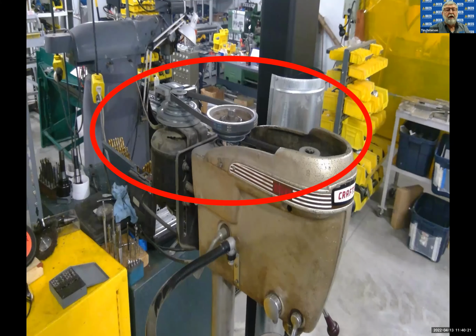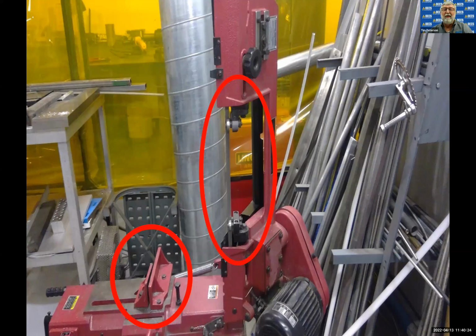The next machine guarding issue that Melissa's going to switch to is one, again, that a lot of people forget about. And this is on a bandsaw. The concern here is, if you look at the two circles, where that piece of metal is placed on the bottom left is very, very thin. So we're probably cutting a piece of metal that's maybe a half inch thick. You look at the exposure to that blade, it's a lot more than a half inch. Get your people to reduce that exposure by closing that guard so that only the point that needs to be cut is being cut with the blade.